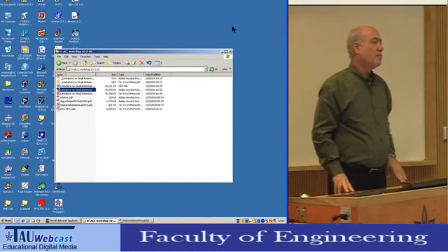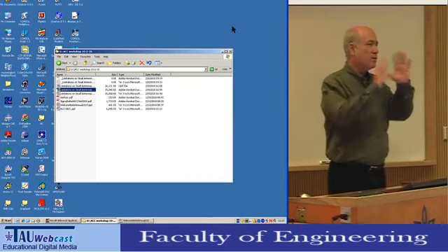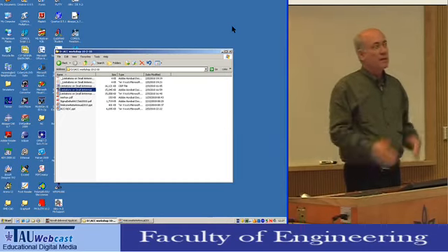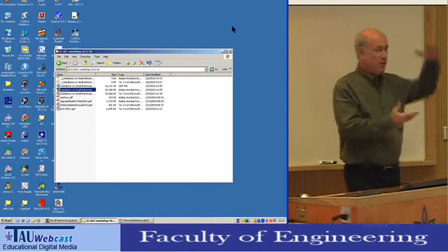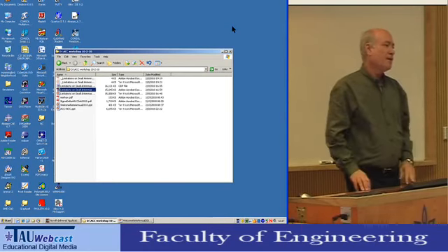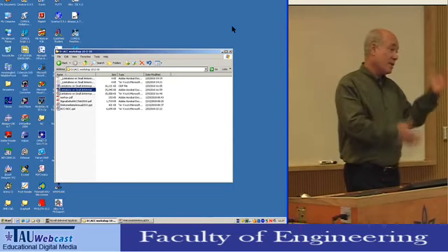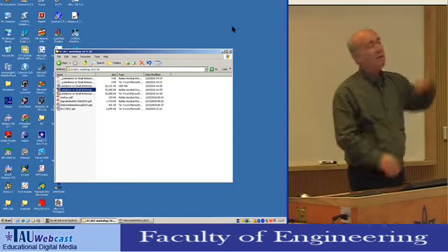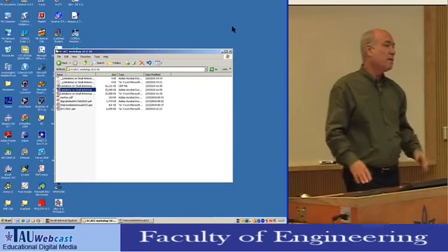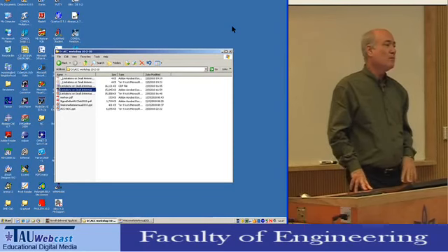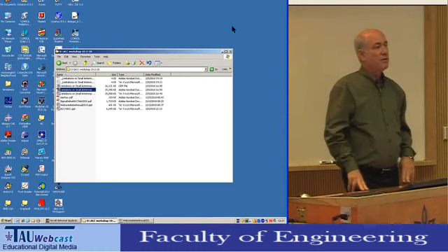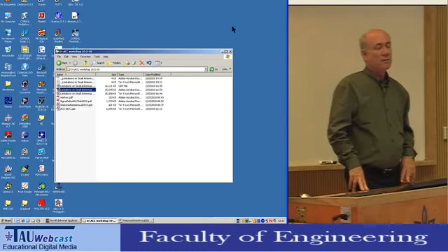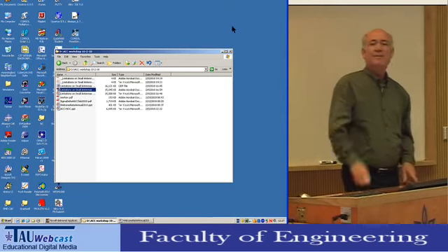True. It will enhance the activity, but the whole structure is about the same. What happens is that you excite the ground plane, so you enlarge the effective area. There's current flowing in it, so a larger effective area, and it happens. So how much can you gain? Well, at the peak, you can gain 6 dB theoretically, tops. Yeah, for the gain.